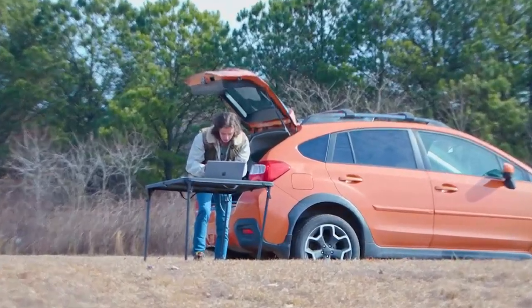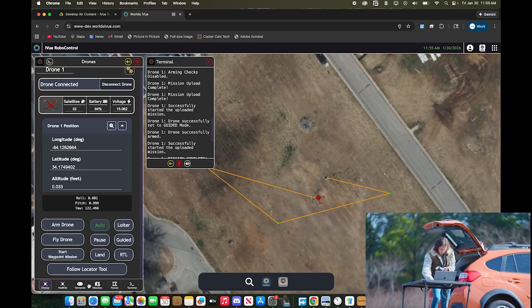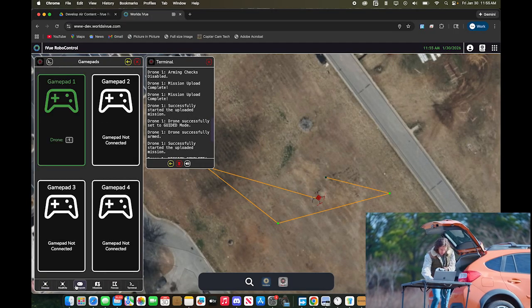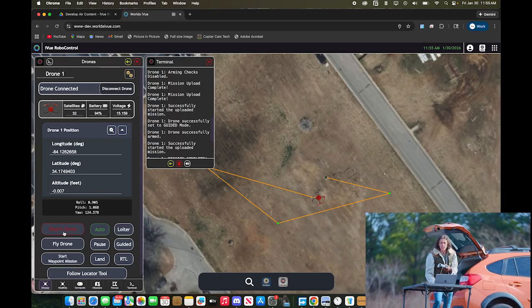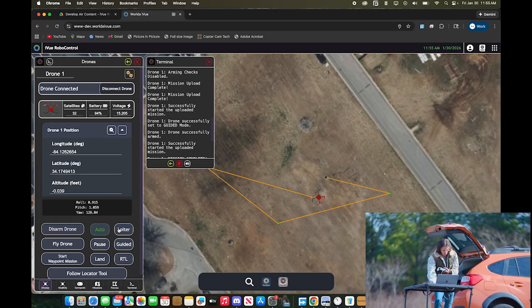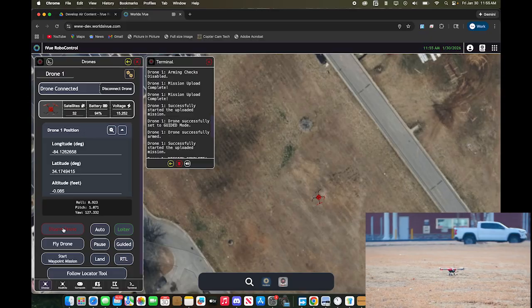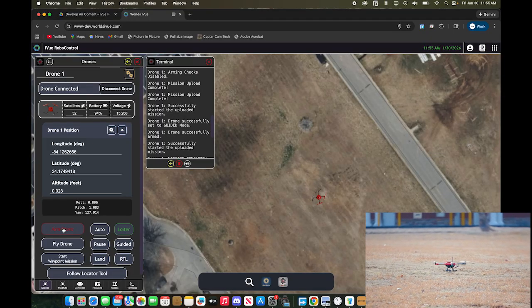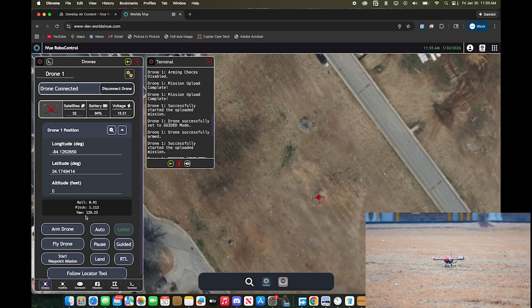All right, and because I can, let's go ahead, make sure the gamepad's connected, and I'm going to verify that the arm and disarm button is working even though there's a UI glitch. It may be more than a UI glitch, but let's find out. Going to set Developer into Loiter mode, I'm selecting arm, and then taking off manually with the controller.